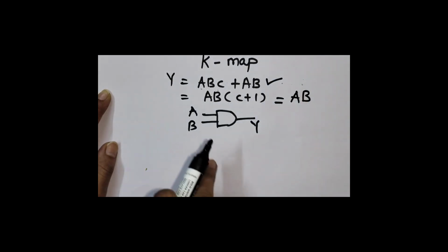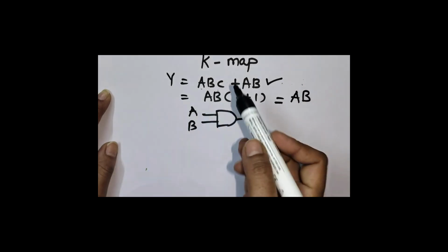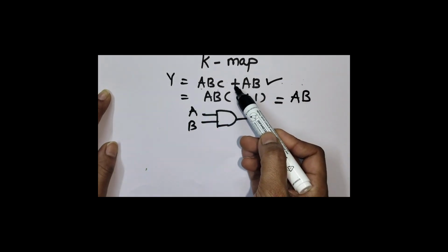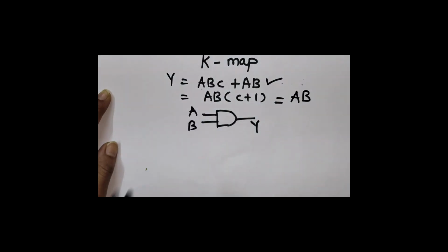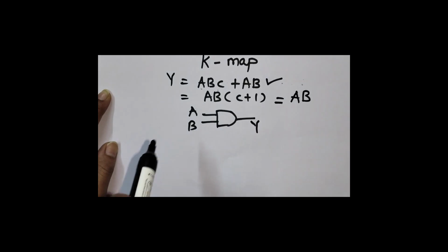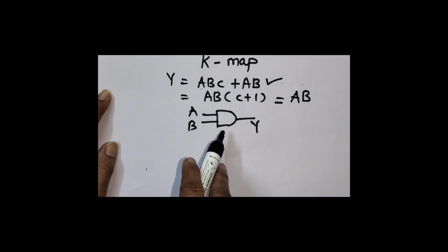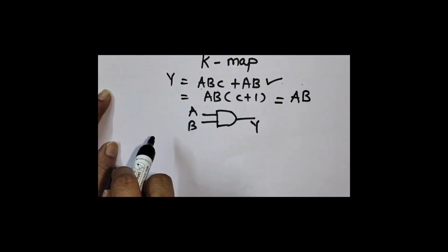Because of reduction, now instead of using 2 AND gates and 1 OR gate, I can implement same circuitry using single AND gate. So space on chip reduces. I need to apply power to single AND gate, so power dissipation also reduces. Then no extra wires are needed.